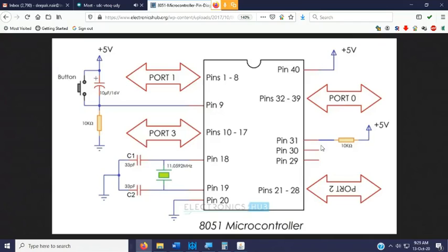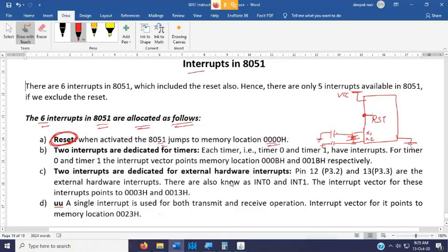Pin number 31, this is VDD, I think, and it is again connected to plus 5 volt. So you have VCC, you have VPP, I think this number is VPP, and then you have ground, crystal, and the connection for reset. You have to make this basic circuit before working with any microcontroller. So what we are doing, we are using a capacitor here, a resistor going to ground, and then there will be a push to on switch.